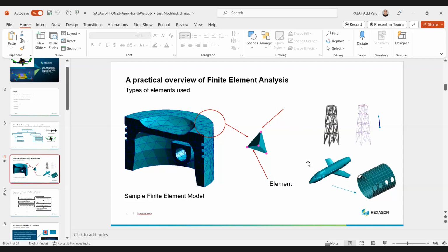So what I can say is I can assign that. So any kind of plane stress condition, those kind of conditions, or any kind of sheet stringer, like if you see an aircraft fuselage, it is a sheet stringer configuration. The sheet is basically the skin around it, and then you'll have your stiffness, and then you'll have your whatever your bulkheads are in the middle, those kind of things. So you can use a 2D shell element in order to create this.